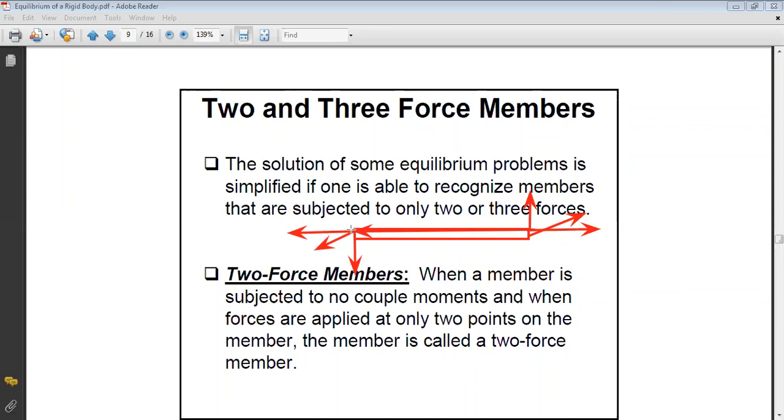And in the exam, the majority of you didn't respond well to this question. I said in the introduction of the course, you have two cases, particles and rigid body. The main difference is that for a rigid body, you cannot neglect dimensions. So the condition for equilibrium of a rigid body is not only sum of forces equals 0, you have two conditions, sum of forces equals 0 and sum of moment equals 0.